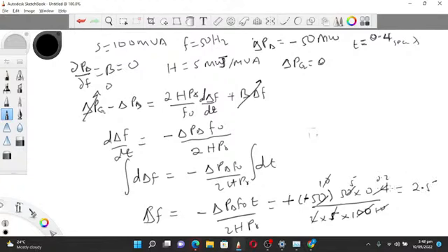So our delta F is 2.5. Sorry, our delta F. Hey, 0.2 times 5 is 1. Please, I'm sorry. Our delta F is 1 hertz. So it's a positive frequency. That means our new frequency, F0 plus change in F, will be 50 plus 1, which is 51 hertz. Okay. So we've gotten our change in frequency now. We've gotten the actual frequency, 51 hertz. So that's it for this question.